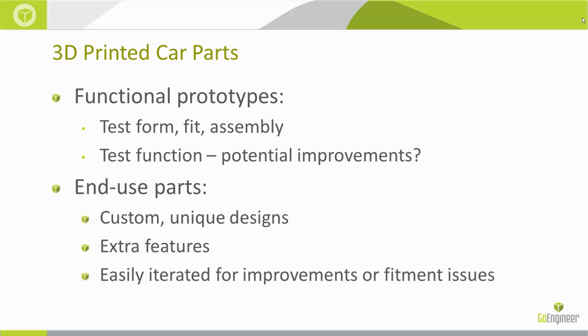So we come in with an initial idea, we need a part to achieve some sort of task, and because we're working with 3D printing, a lot of times you can add extra features at little to no cost. I'll talk about a couple examples of where I did that in my process, and this can be a great thing because you end up with smarter, more intelligently designed parts, but it can also be a bad thing too because you tend to get feature creep, meaning you design a part to do one thing and you tell yourself, you know what, if I spend a half hour more, I can add this feature. And you do that 5-6 times and all of a sudden you've got a Swiss Army part that you really didn't want. So feature creep is something to be aware of.